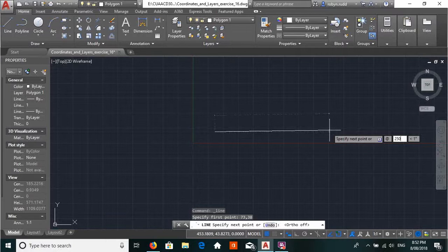If I give the at sign and 250, you can see there's a little angle sign there. It's prompting me to say at what angle. On your computer keypad, you'll see a Pac-Man or greater than sign, next to the capital M. So press Shift greater than and give the angle, which is 0.